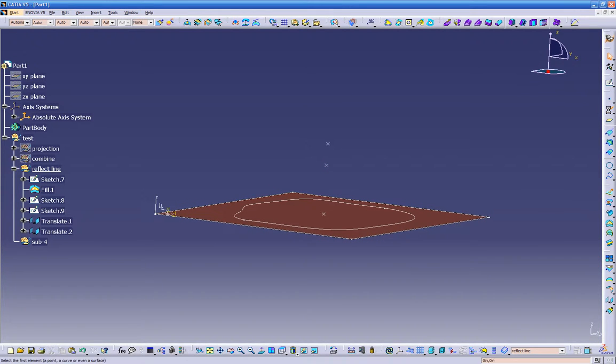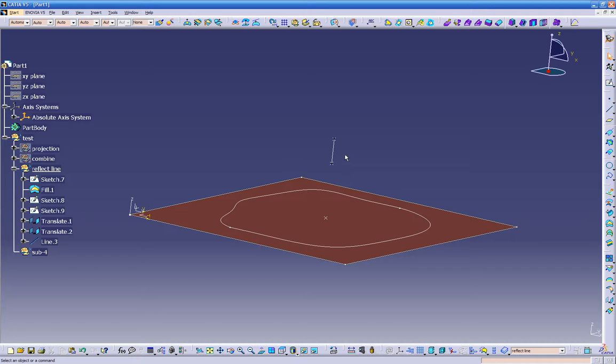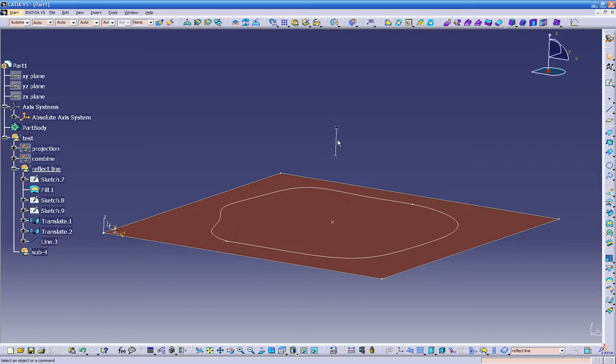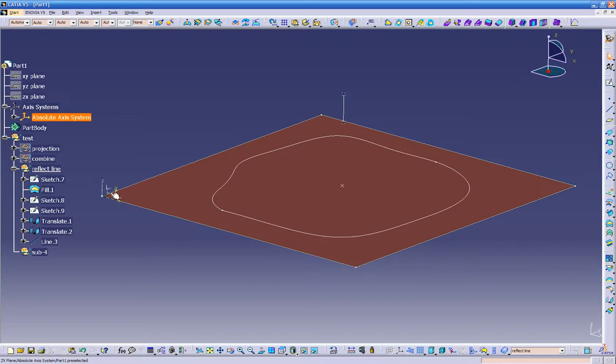Now let's create a line. What I'm doing is creating a line and points in a 3D view. They're not in a sketch. If you click on the line, you can tell right here it's just a line. It's not built in a sketch. We can do the same thing in a sketch. I can just take this plane, offset it all the way over here, and open a sketch. As a matter of fact, let me do that pretty quick.